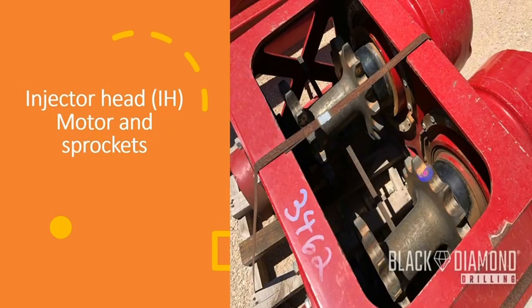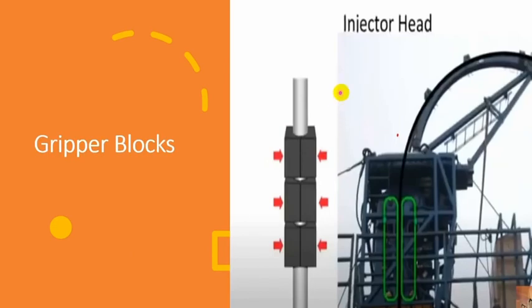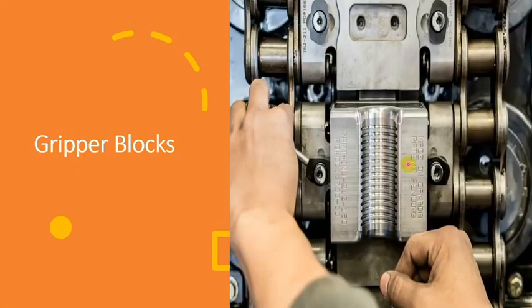Here we can see sprockets. As you see, here is a sprocket and a sprocket. These are the driving sprockets connected to hydraulic motors. This red one is a hydraulic motor, and also this one. When it rotates by hydraulic pressure, it rotates the shaft connected to these chains. Okay, so these are the sprockets from above, with grabber blocks surrounding the coil tube, and as it rotates with the chain, it injects or pulls the coil tube in or out of the well. This is a single grabber block.